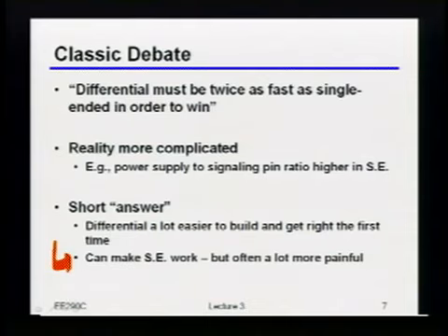Well, so there's no fundamental reason why single-ended can't get low BER, right? So remember, that's why I'm going to try and use the distinction between noise and interference. What typically limits a single-ended link is not noise, it's interference. So the question about getting it to work is really a question of finding what's actually causing the interference on your signal and figuring out how to get rid of it. So either adding more grounds, adding some shields somewhere, increasing the swing so you get more margin, doing a better job of coupling the reference to your actual signal, and so on and so forth.